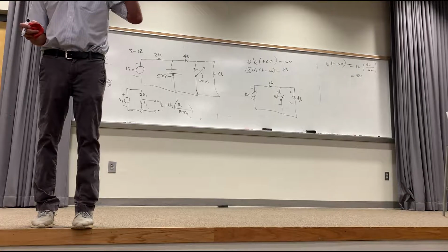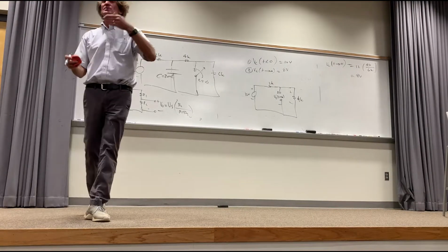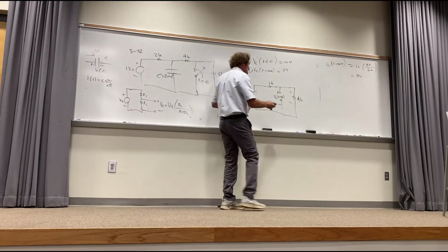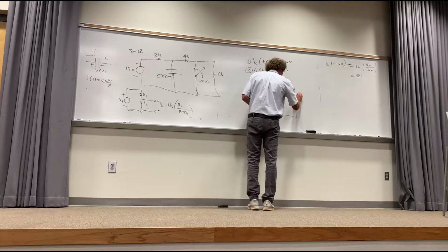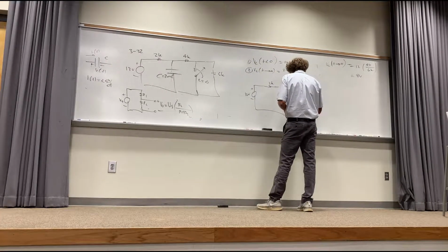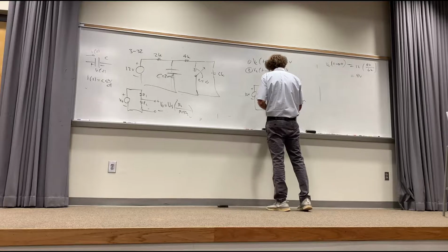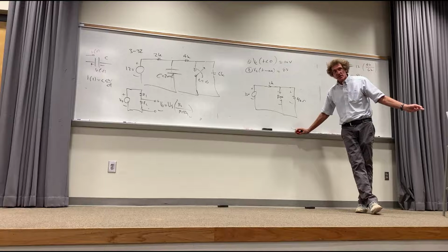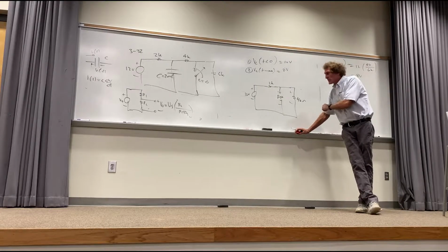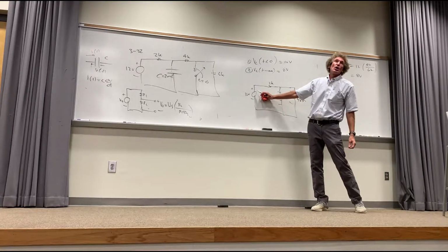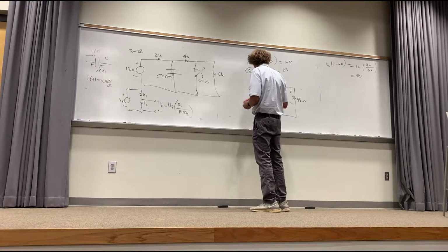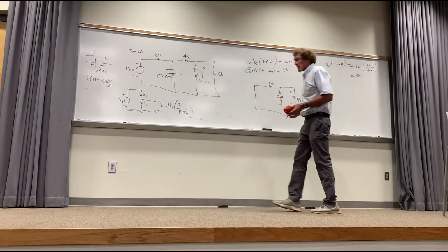Now, what's the next thing? We have to calculate one thing. Anybody? R Thevenin for t after the switch closes, or for t greater than 0. So it's this R Thevenin, right? That's after the switch closes. It looks like that. That's 4K. So what is R Thevenin there? Well, for R Thevenin, what do we do with the sources, class? Turn them off. What does a voltage source become? Short circuit, a wire. If it was a current source, it would become an open circuit. Short circuit.